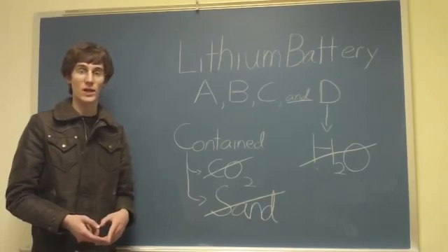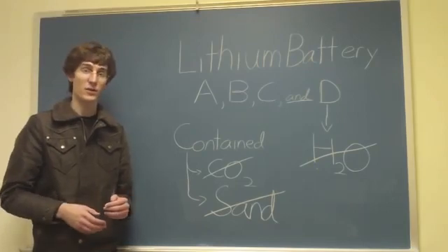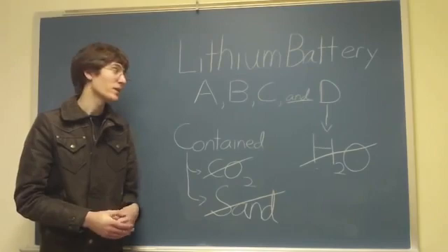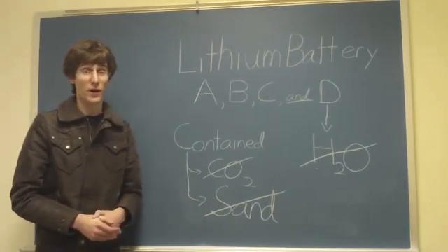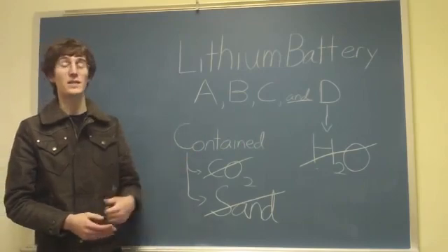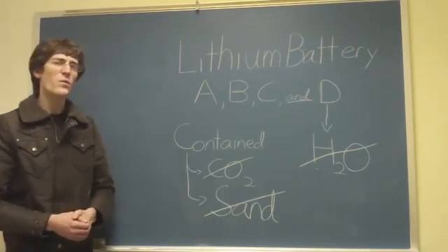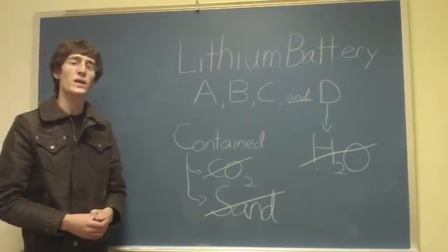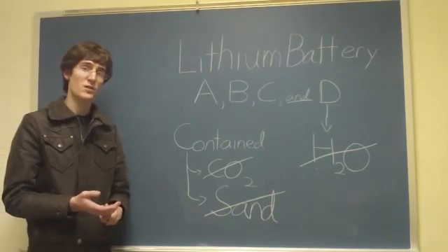That's called an electrolyte, and it is between the cathode and anode. Because this is a battery, it's obviously also an electrical fire. And lithium, being a metal, makes it a Class D fire. So we have to think a little bit about how we might want to put this out. Remember, we can get rid of the heat, the oxidizer, or the fuel.